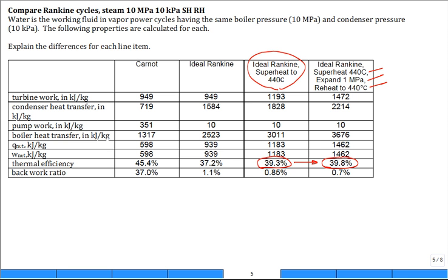If you start to get 4 or 5, it probably appeals to your logic that it's going to be more complex to build, maintain, expensive, probably not worth the return in performance. So often in power plants you'll find 3 stages, maybe 4, not 1. You'd have more stages, and you'd go back. You'd have all this piping going back for reheat, then coming out. All right. Well, that's one way to improve. You had reheat and you had superheat. Okay. What's the other way?